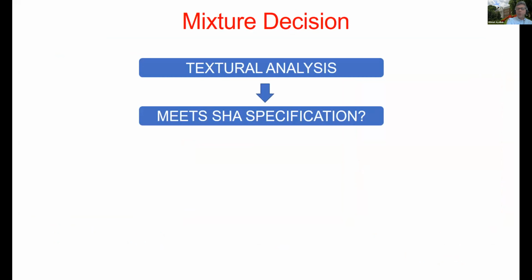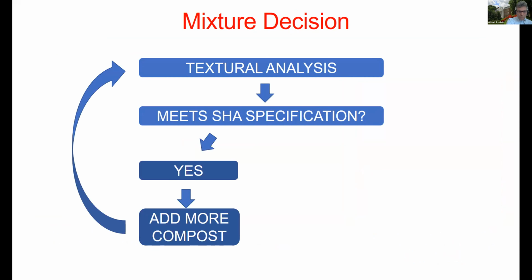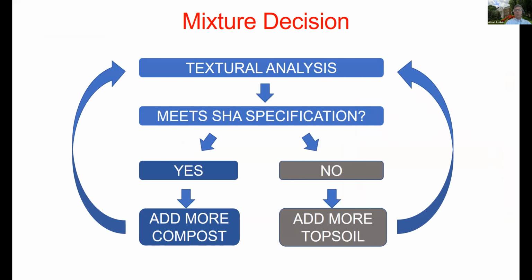If you look at the local jurisdiction, it requires you to look at a textural analysis. Let me actually maybe go one by one so it kind of helps. Look at the textural analysis, and textural analysis here is nothing but grain size distribution. There are different names in this design system or in this engineering, and the term that we use commonly, grain size distribution, coincides with the textural analysis. In the textural analysis, they typically use the USDA, United States Department of Agriculture system, for obvious reasons.